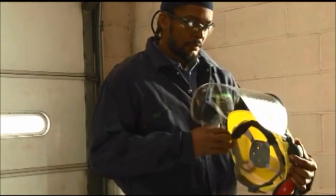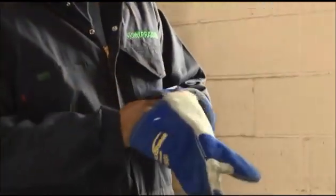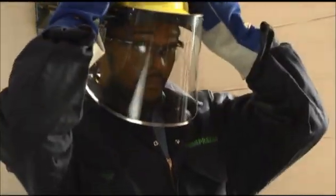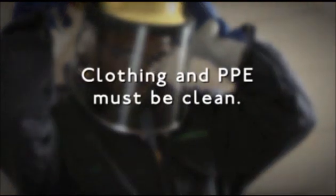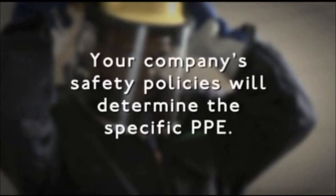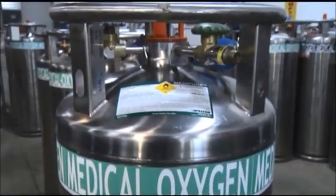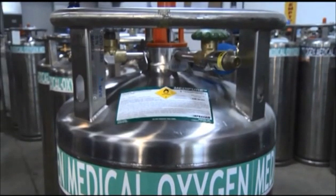Typical PPE includes safety glasses with side shields or goggles, which protect against pressure, covered by a full face shield to protect against splashing. Also wear loose-fitting insulated cryogenic gloves, flame-resistant long-sleeve shirt, and pants without cuffs. All clothing and PPE must be clean and free of contaminants before working with oxygen. The type of work being performed and your company's safety policies will determine the specific PPE to be used. As stated earlier, some materials become extremely brittle when exposed to the extreme cold of liquid oxygen. For this reason, only use containers, equipment, and systems designed to handle the extreme cold of cryogenic liquids.